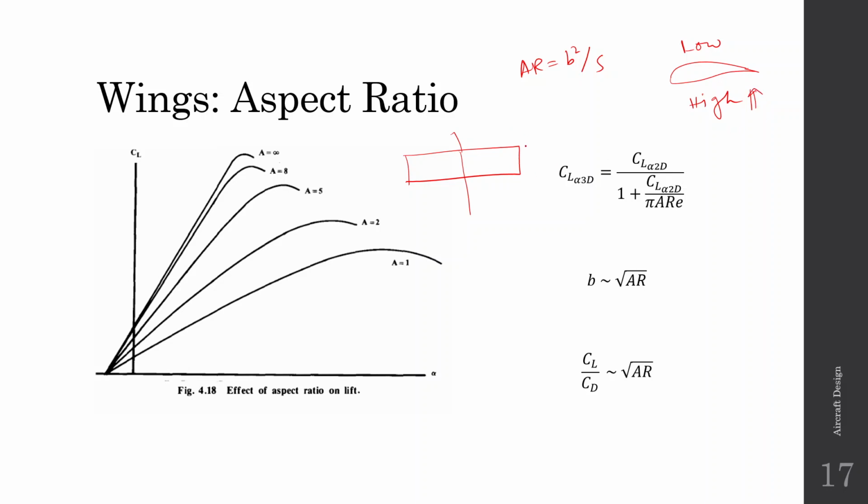Now at the tip, since there is no obstruction at the side, the air flows from the high pressure section to the low pressure section towards the tip. So it comes like this, from below the wing to above the wing, and since the aircraft is moving forward, this creates vortices towards the tip.